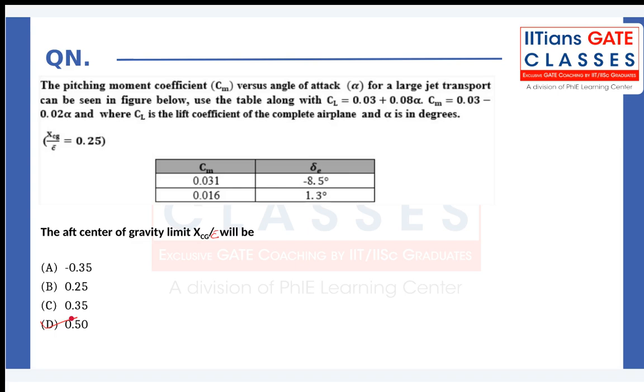Dihedral wing for longitudinal stability. So let's think about that. Dihedral angle is usually introduced for lateral stability. For longitudinal, it is just high and low wing configurations. And for dihedral, it would be high wing configuration. And what we have seen right now, as far as our justification goes, high wing is not longitudinally stable, right? Which we will have to look into. So just maybe wait till the next class when I find out whether the high wing low wing justification that we had is right. If it is right, then dihedral wing alone will not be longitudinally stable, is what I believe.